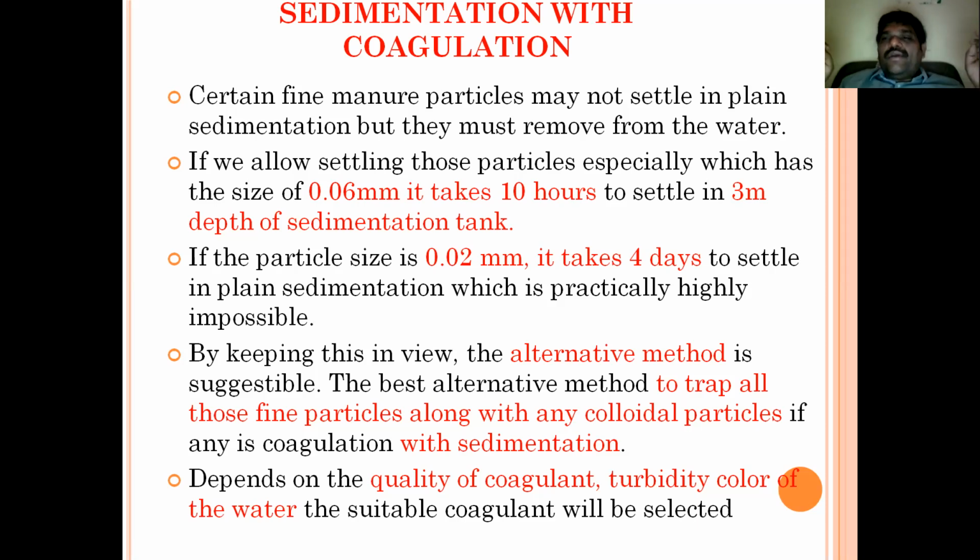If the particle size is 0.02 mm, it takes 4 days to settle, and we would need to wait almost 4 days for only the sedimentation process. Sedimentation is the first step of treatment. There are many more steps to be conducted before the water is sent to the public.